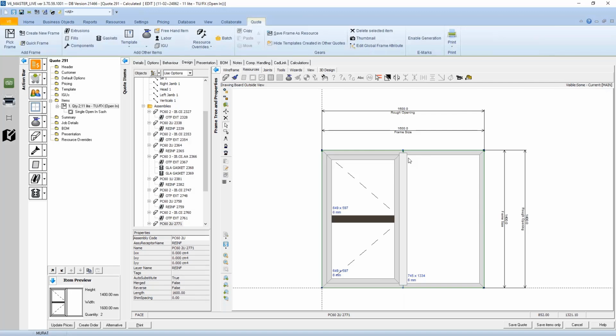Let's say we have a curtain wall system, and if it is structural silicone glazed, SSG, then as a first level you have the back member, then after the back member you have the silicone assembly, and that's it. However, if we do a captured one, then we have the back member, then the thermal heat barrier, after that the pressure plate, and after that the cover cap, and all are child assemblies.